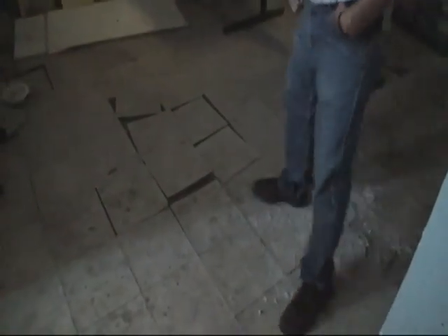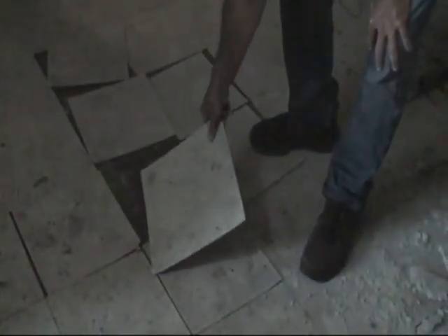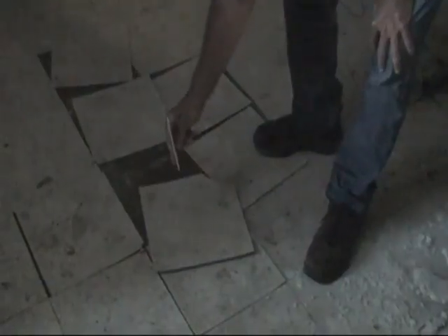Other thing, floor tile is considered a non-friable, typically non-regulated asbestos containing material, but it's contingent on the condition of the material as well as the work practice that's going to be used. These particular tiles have got wet and floated off of the floor, and while they may have been resilient when they were put down, if they were at all brittle at the time they were removed, they may need to be handled as a regulated asbestos containing material.